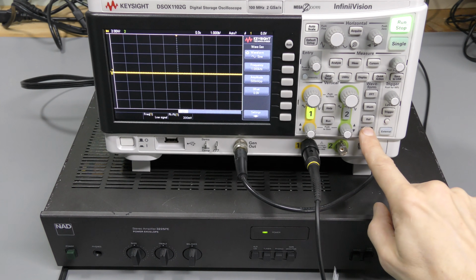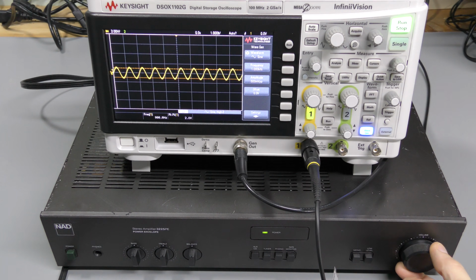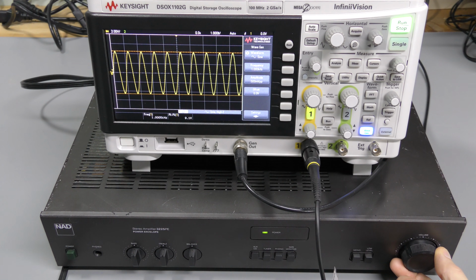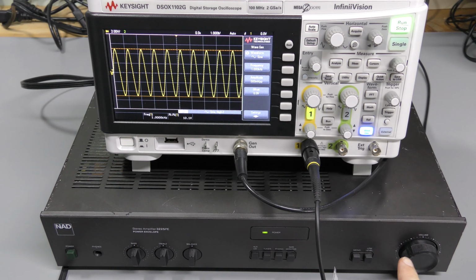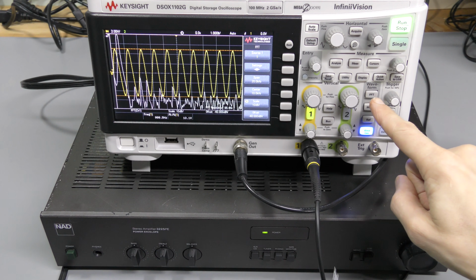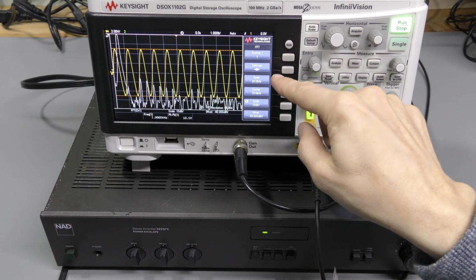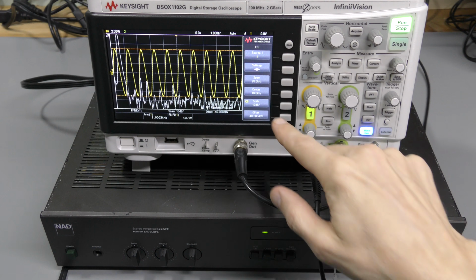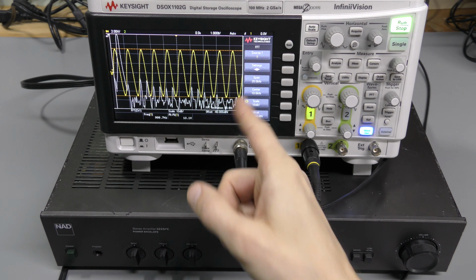So let's turn on this function generator, and now if we turn up the volume we should see some output. Let's say around 10 volts peak to peak when the volume knob is slightly above 10 o'clock. So now we should be able to look at f of t, and I already adjusted the range here, so the span is 20 kHz and center is 10 kHz. We are looking at the range from 0 to 20 kHz.